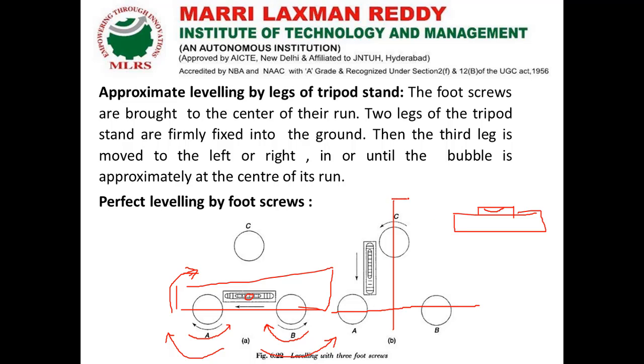Adjusting only the one remaining screw, either clockwise or anti-clockwise, the bubble comes to its center position. Once it reaches its center position, we stop the process.